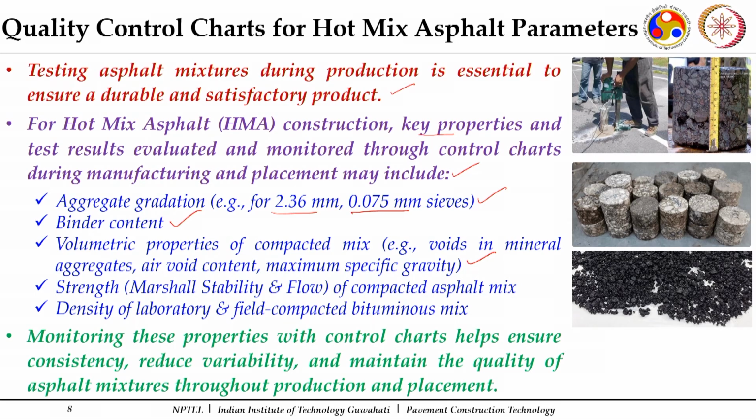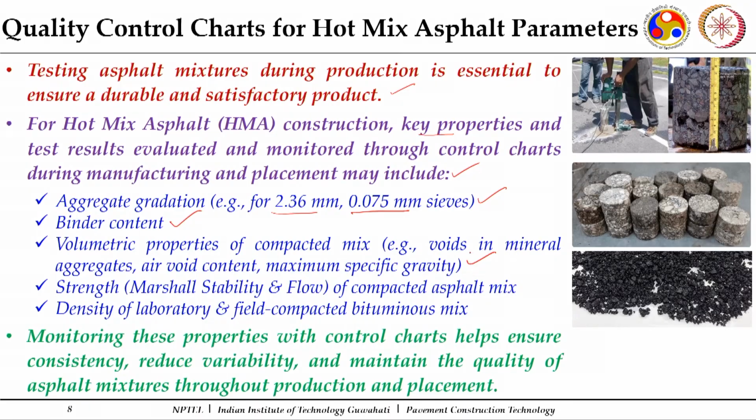You can look for the compaction of it. Similarly, you will prepare the samples at the laboratory setup at the plant also. From there also you will work out the volumetric properties, and especially what volumetric properties are considered. This is voids in mineral aggregates, air void content, and theoretical maximum specific gravity. Now, strength along with it, on compacted samples, strength and flow are the other characteristics.